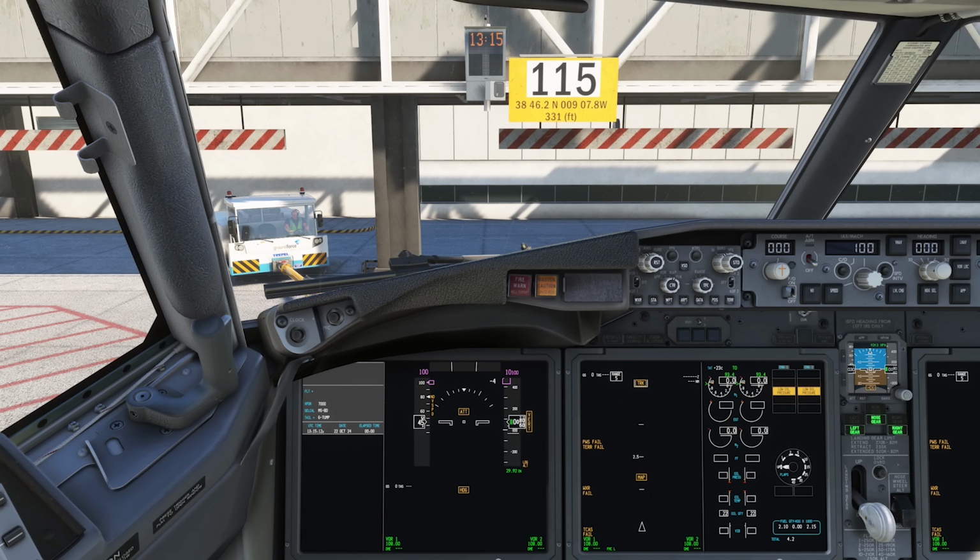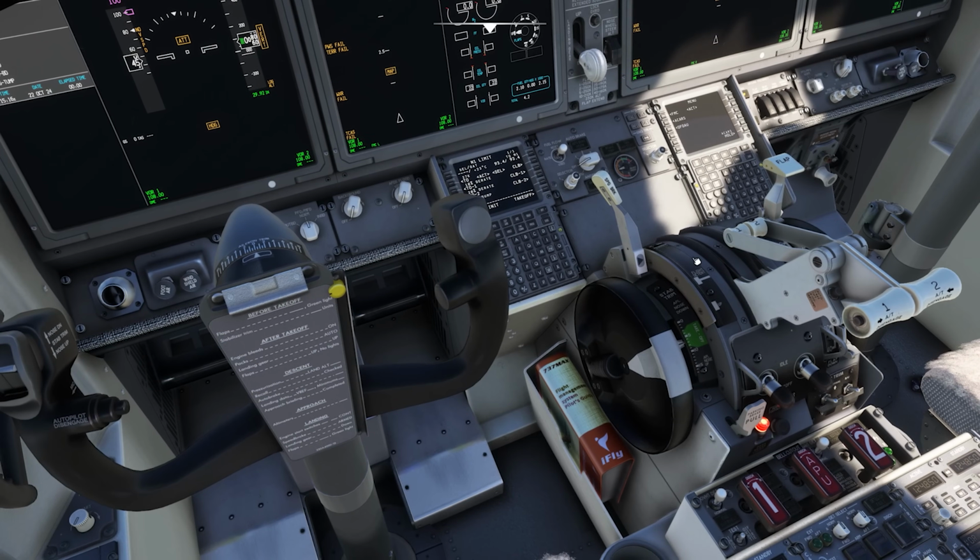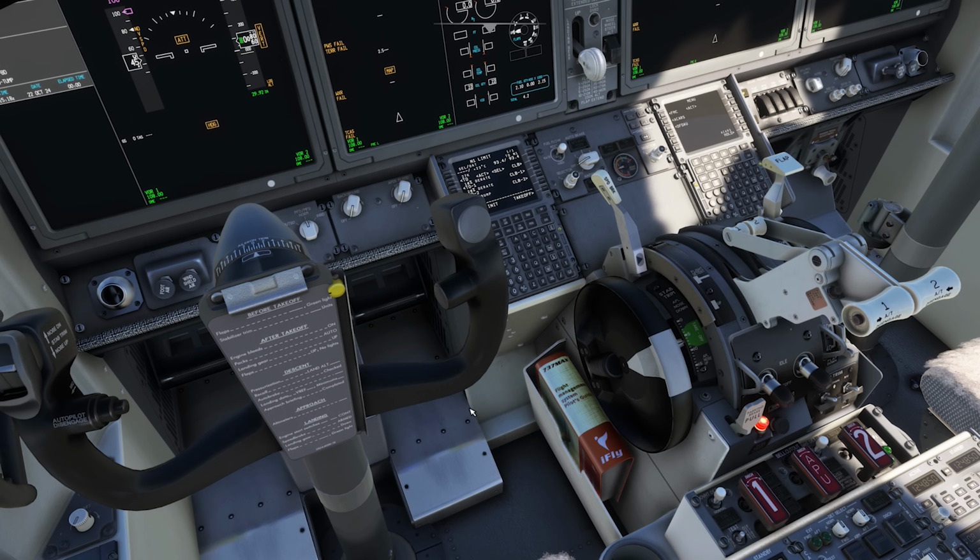Lastly, and again transparent to the flight crew with the speed brake, is EDS, which is the emergency descent speed brake. So if you have a rapid depressurization and start descending very quickly, it'll detect that this is the case, and you pull the speed brake to flight detent. What happens is that the speed brake or flight spoilers extend slightly beyond the normal position, giving much higher rates of descent. Again, this is very evident when we're practicing rapid depressurizations and emergency descents in the sim, just to get down as quickly as possible.